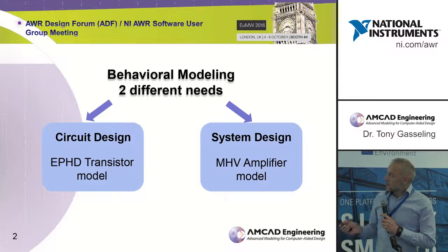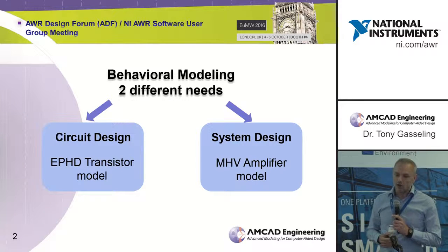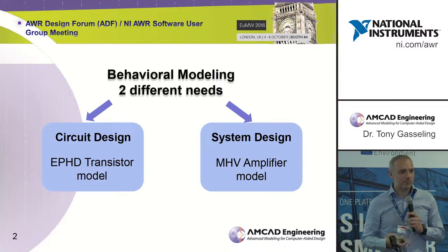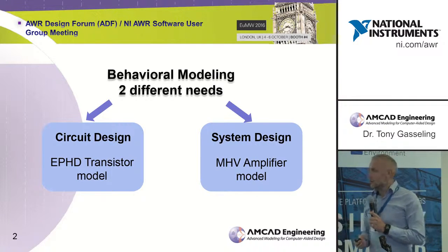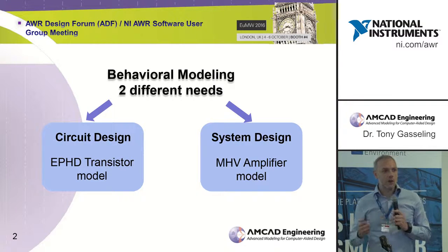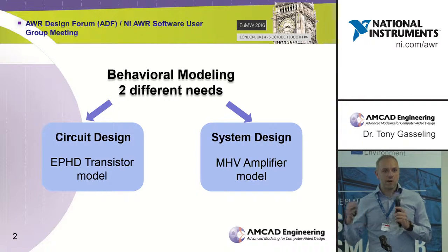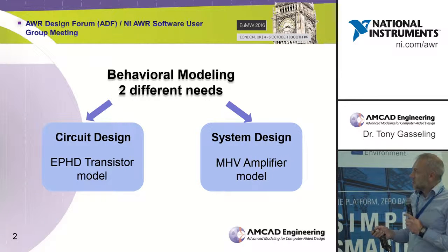And the other family of models are rather dedicated to circuits, such as amplifiers. So when dealing with amplifiers, the need is not exactly the same. That is to say, we don't care about the influence of the loading impedance. We are much more dedicated to the model performances when we are using modulated signals, let's say wideband modulated signals, because this is a trend now to have wider and wider spectra. So here the needs are not exactly the same.